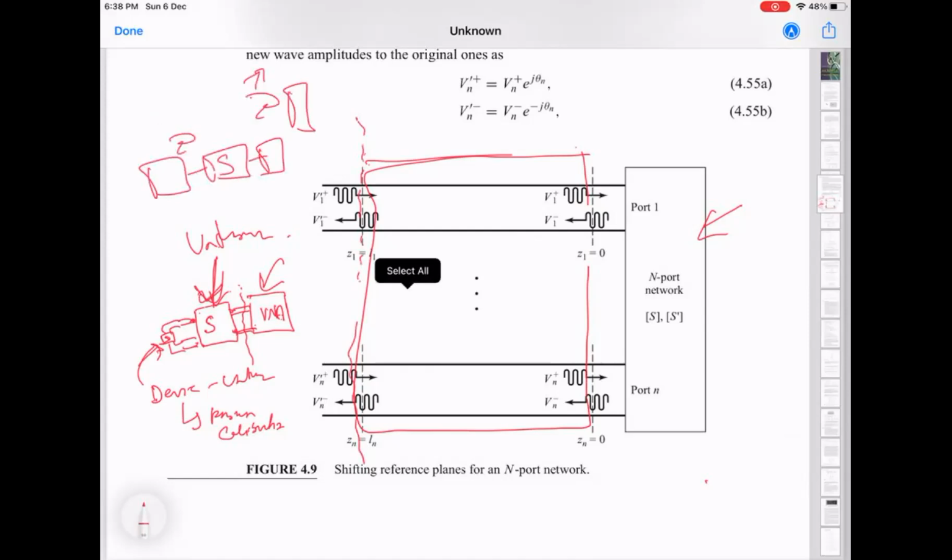So you're actually measuring gamma prime. Then you want to know, okay, what is really gamma of this device. So you replace this with some different standards, and typically these are simple things like an open, a short circuit, and a 50 ohm, because these are the simple standard things. And from that, for a single port with these three measurements, you can actually recover this unknown S matrix in the middle.